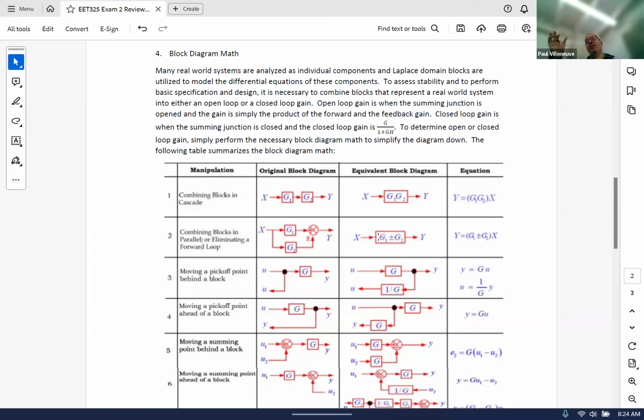But in the real world, most of us, at least I'm not smart enough to be able to look at a system and say, here's the simplified equation of the system. So what I need to do is take one piece at a time and figure out how to model that system. And then I assume that there is enough difference between the two system blocks that I'm modeling so that interstage loading doesn't impact it all that much. So I can model part of this system, next part, and then I can put them all together and have a reasonably accurate system. And so when I do that, I create many of these little blocks, maybe hundreds of these blocks, that I need to combine down into one simplified block so I can solve for the characteristic equation.